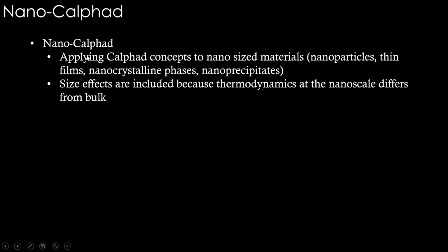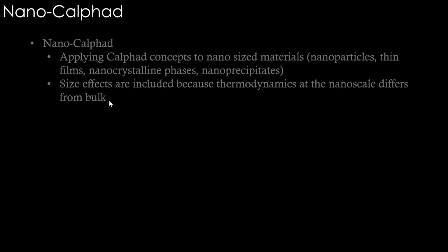This nano CALPHAD, including size effects in thermodynamics, is basically applying CALPHAD concepts to nano-sized materials: nanoparticles, thin films, nanocrystalline phases, nanoprecipitates inside a matrix of a bigger size. All these things have something extra compared to the normal thermodynamics that you have been focusing on, that is the surface effects. So when we go to these sizes, we get these size effects, because thermodynamics at nanoscale differs from bulk. We'll see how to do that.